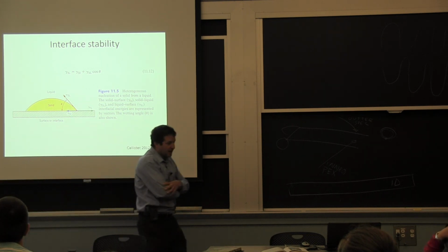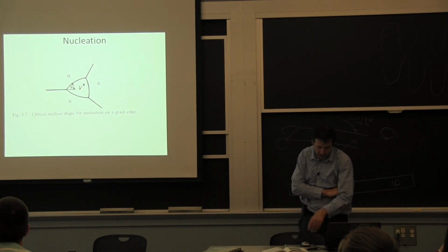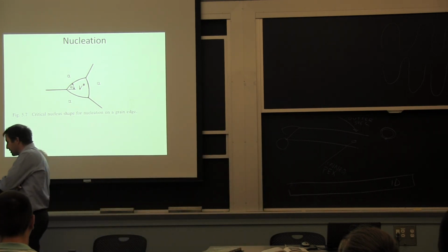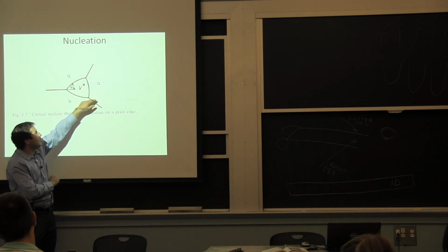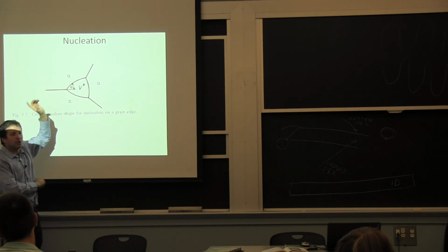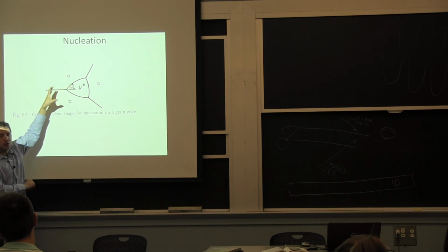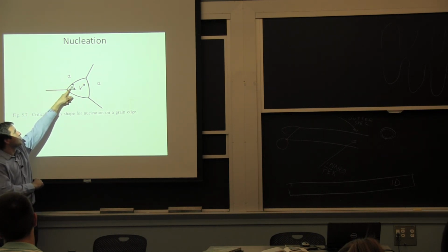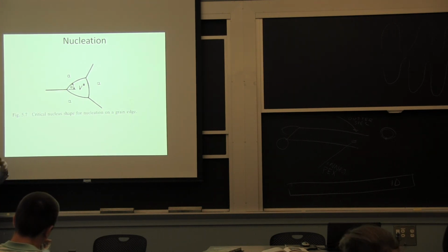There's a significance of that in any of the processes for forming precipitates, for forming grain growth, for recrystallization. If I start at an interface, so this is essentially a triple point in a grain of your material, and you're trying to come and arrive with a new face, there's going to be this critical angle to tell you whether you're going to grow or shrink. What's the equilibrium? So there's going to be a critical size where you can reach the angle that you are interested in to start forming and growing that process.